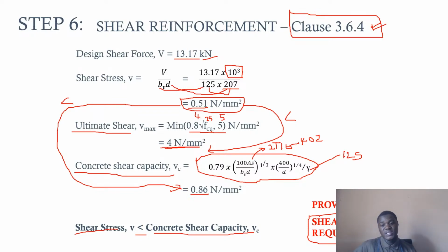And the code recommends that you can provide that at a spacing of 1 meter or 1.5 along the rib beam. So that's why we said here to provide T8 bar at 1 meter spacing. So this one is just to hold the design reinforcement, the tension reinforcement, together. So that is the main purpose of this link reinforcement we provide, T8 at 1 meter.